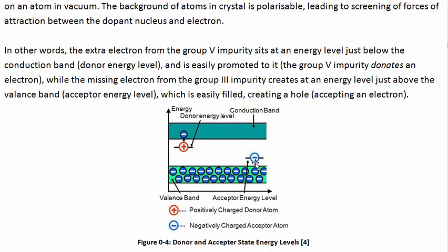Looking at the band energy picture, we've got the conduction band up here. There are very few electrons in there, but if there are some, because there's a lot of empty states to move into, they can move back and forth in there under the application of an electric field easily. In the valence band, there are not many states that are empty, but if we were to make an empty state, then all the other electrons could move into that, and so it's like the state could move around. This is where holes exist, and this is where conduction electrons exist.